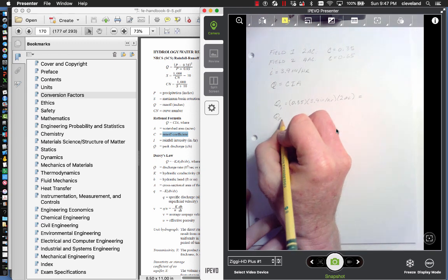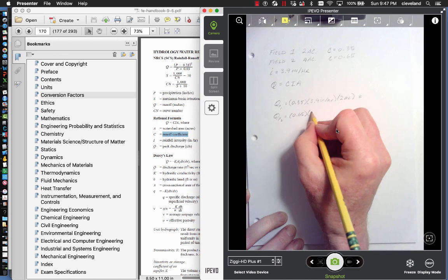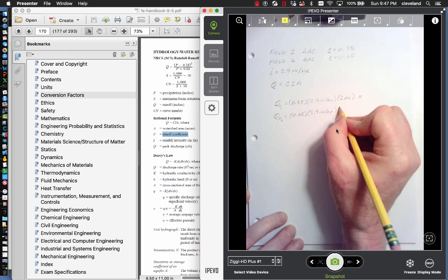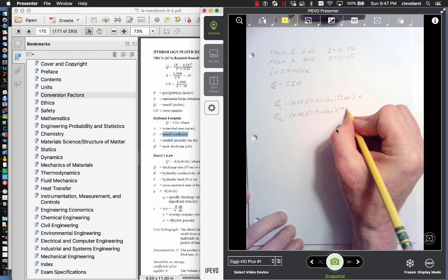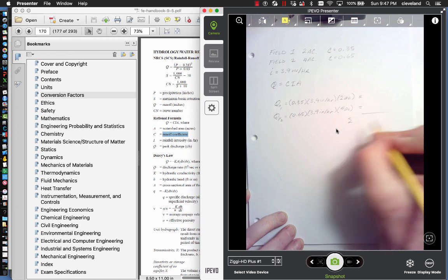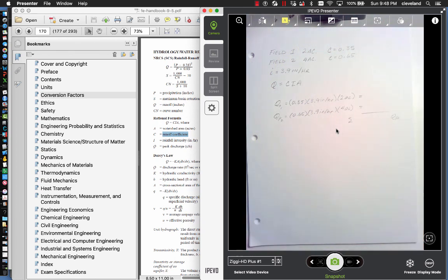And Qp2 is equal to 0.65 times 3.9 inches per hour times 4 acres. That will equal something, and the sum would be the Qp that we'll use to choose an answer from.